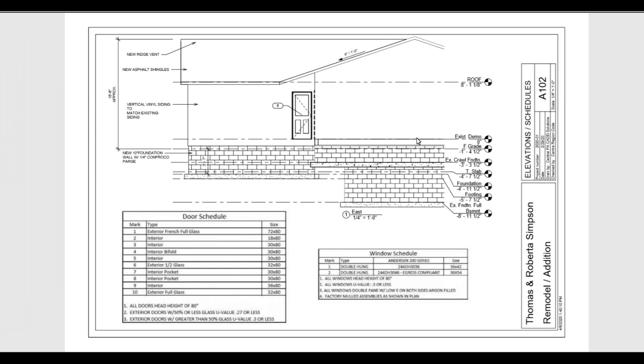So at this point right here, this is 0 feet 0 inches, and that's really going to represent the floor level. And then everything that I do works off of that. So the new roof line, or where the trusses would sit on top of the wall, is going to be 8 feet 1 1/8 inch above 0, or above that first floor subfloor level, and then we work everything backwards from there.